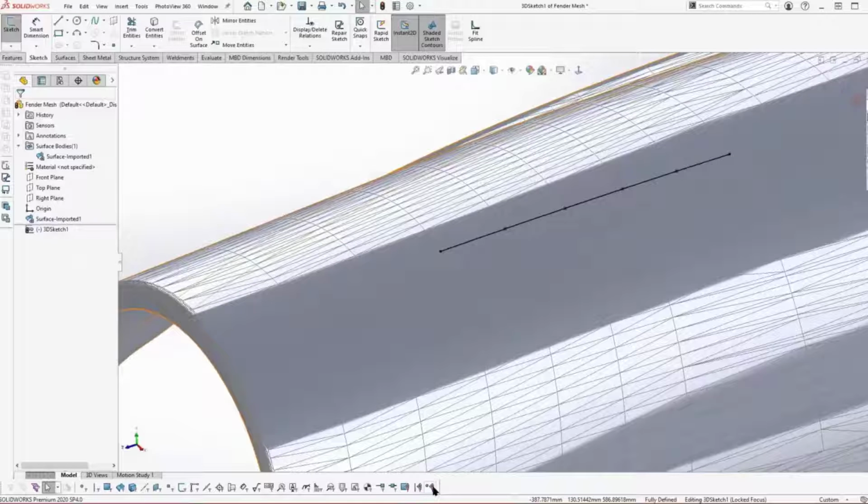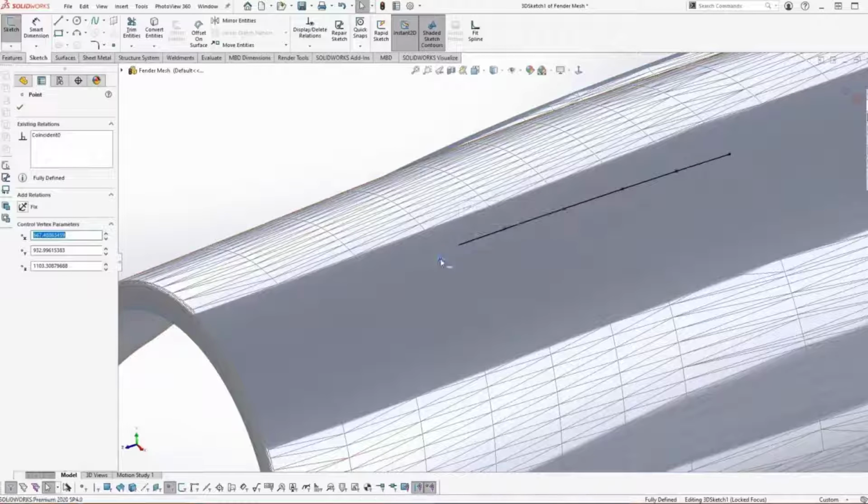If you notice down here on the filters toolbar, there are some filters that we can use to select those types of things. But if we have those filters turned on, we'll notice that things like selecting relationships there, I can't select that relationship. So if I wanted to delete it to be able to move that, I have to go do that from the tree.